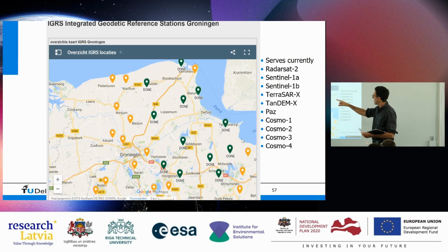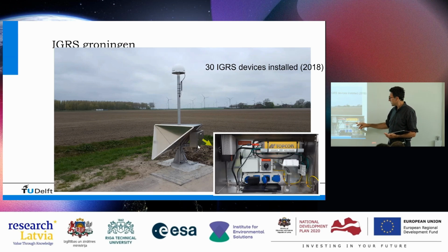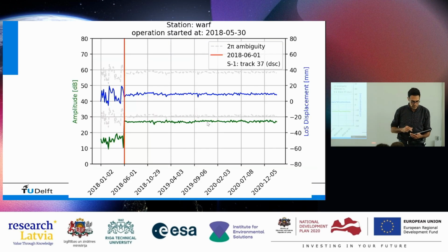So this is in the northern area over here. And so that means that for all these satellites with SAR sensors, we can follow that. Inside there is a little cabinet, so the radar reflections are passive. They are just simple reflectors. And here we have then the GPS receiver and a modem and power supply and so on, and a little bit of heating.